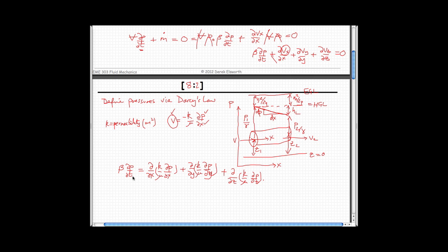So we've done nothing except for conservation of mass, right? We haven't solved for momentum. We've kind of locked in the fact that we can account for frictional losses in some approximate way by using a coefficient which allows us to do that, which basically says that the frictional losses, instead of being proportional to the velocity squared, they're basically proportional to the velocity.